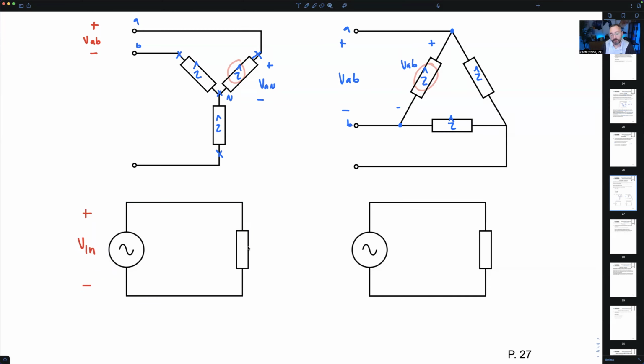What's my impedance? This is going to be one phase of a Y connected impedance. This is this value right here. My impedance is already Y connected first, so whatever the numbers are here, 1 plus j2, 3 plus j5, they go directly in this box.